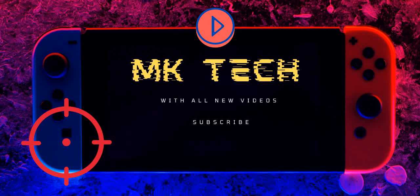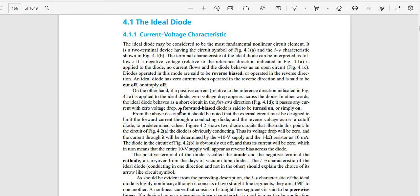In this video we discuss diodes: diode introductions, parts of diodes, and their applications. Number 1, the ideal diode. Current-voltage characteristic. The ideal diode may be considered the most fundamental non-linear circuit element. It is a two-terminal device having the circuit symbol of figure 4.1a. The IV characteristic is shown in figure 4.1b.